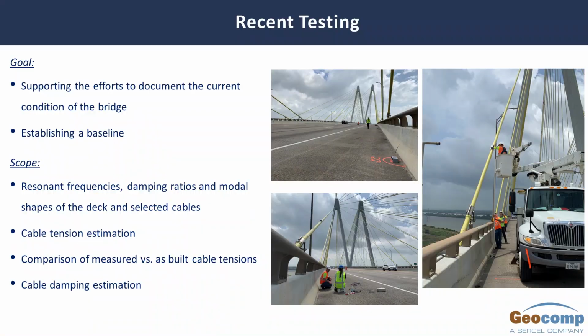The goal of our project, after all those years, was looking at how the bridge was doing dynamically. The idea was creating a new baseline for the bridge through operational modal analysis, and looking at how the deck and cables behave together as a system. Sometimes we see presentations where we test structural components specifically. If we are doing an NDT study, we can easily understand delaminations and discontinuities in those members. However, sometimes when we do measurements, we forget how the system collectively behaves together.